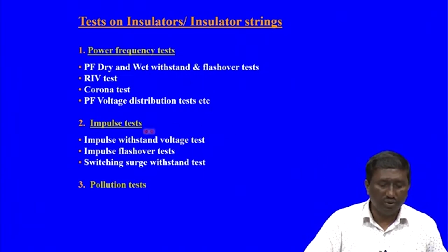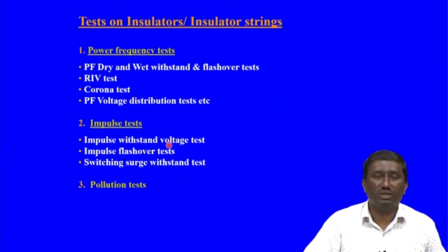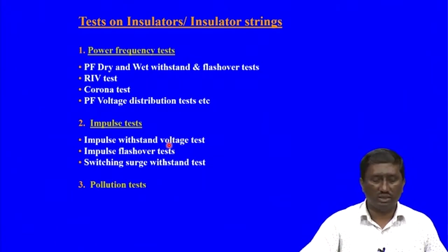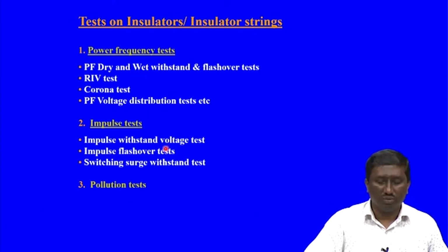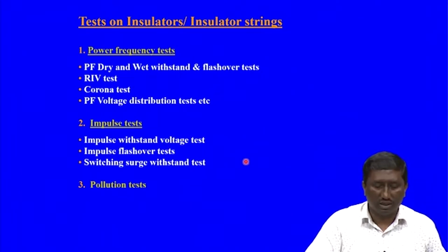The second is the impulse. Impulse is surge test. So, impulse or surge test is again basically to see the withstand voltage level. So, for 220 kV what is the minimum impulse level which it has to withstand, the standards have prescribed the values. So, those values have to be withstood by the equipment when impulse of 10 applications of both positive or negative, or 5 applications, whatever the manufacturer and the utility prescribe as per the standards, the equipment should be able to withstand that number of applications.